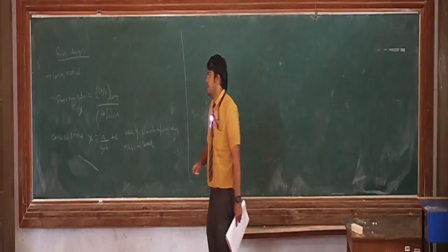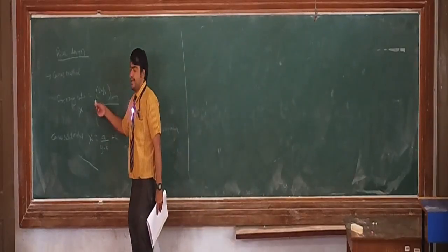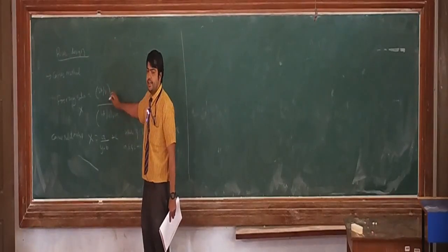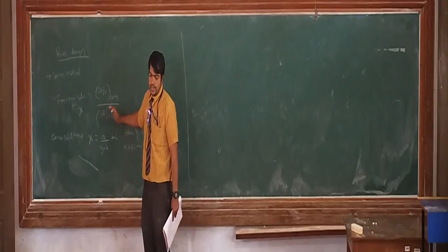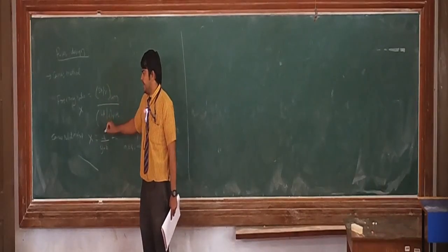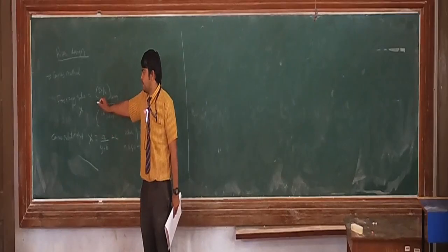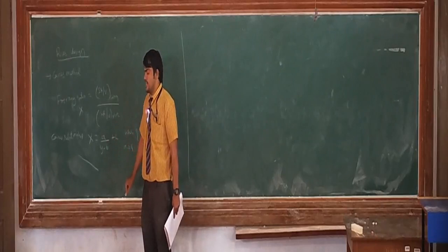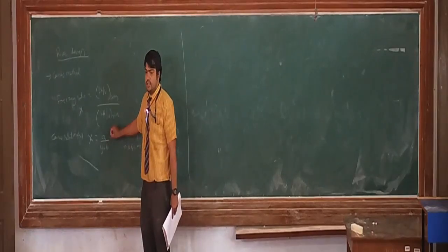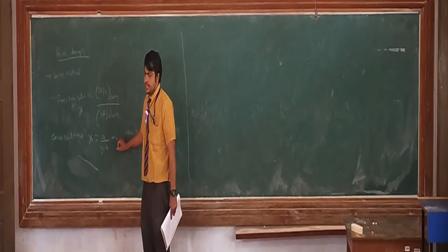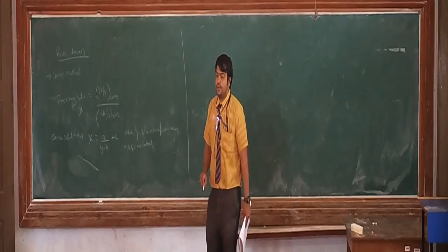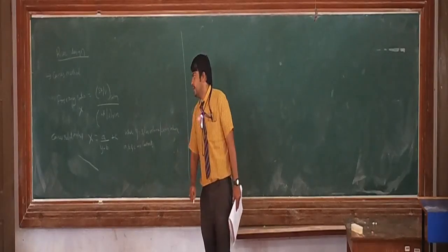So in general, freezing ratio X is given by surface area to the volume, that is cooling characteristic of the casting, divided by cooling characteristic of the riser. Here Keynes relationship with respect to X, that is the freezing ratio, is X is equal to A divided by Y minus B plus C. A, B, C are the constants and Y is the ratio of the riser volume to the casting volume.